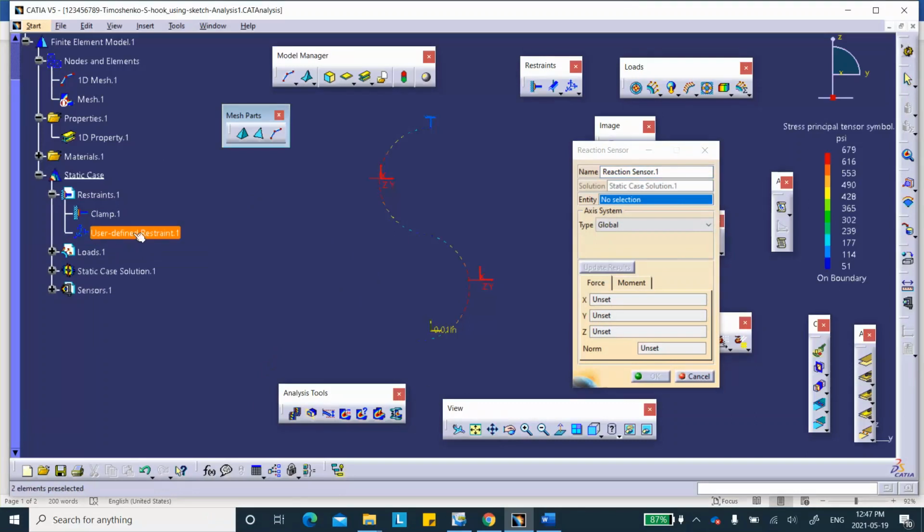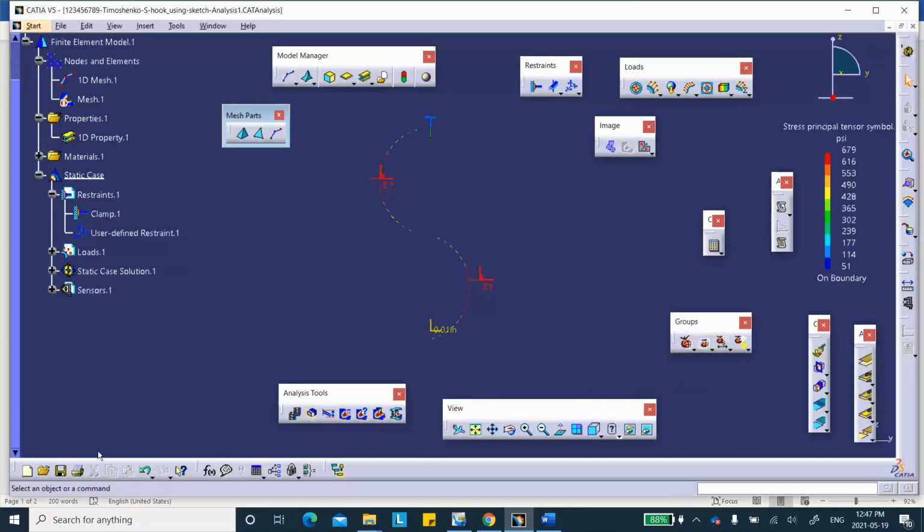You can do it easier from the screen, or you can do the clamp, because the force on that restraint and the force on that clamp will be the same. Either way, update, and you need 530, almost 36 pounds to pull this thing down. Do not multiply this by 2 or anything. That's the force that you need. Okay, save it.